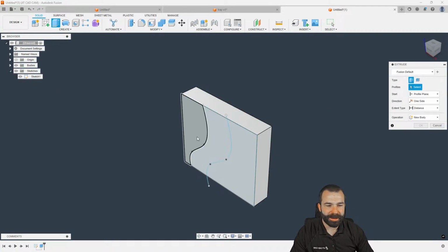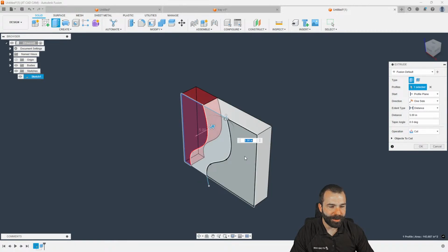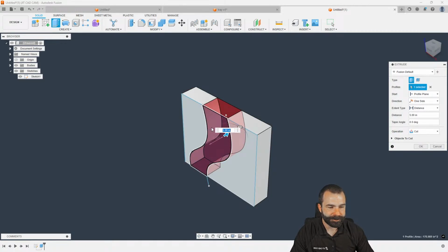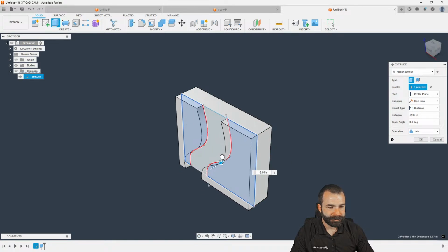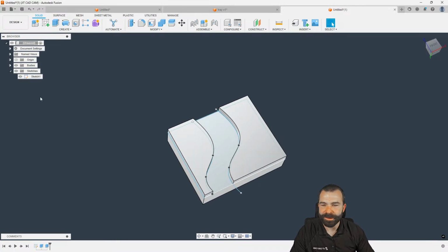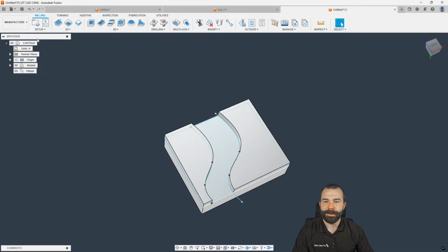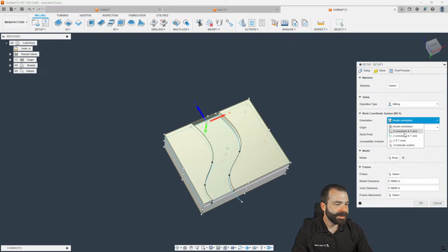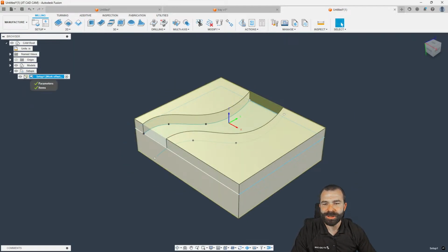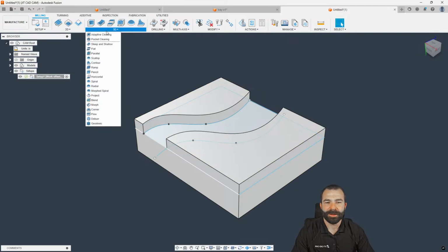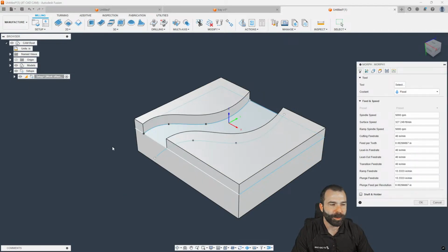And we're going to go back and kick that on. And we'll start with a valley, right? Obviously, it was thinking valley a little differently than me. But, all right. So, going back to the manufacturer side, yours truly doesn't believe in ever drawing a part in the right orientation. So, let's get our Z-axis set. And now let's go look at that actual morph toolpath.